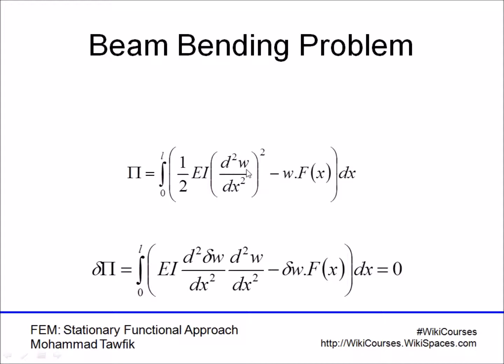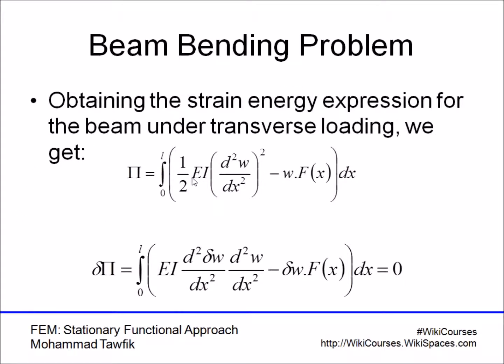Anyway, details of the derivation of the equilibrium equations for a beam can be found in other lectures. What I'm interested in here is that the stress times strain term will be replaced by the modulus of elasticity times the second moment of area multiplied by the second derivative of the deflection, d2w by dx2.